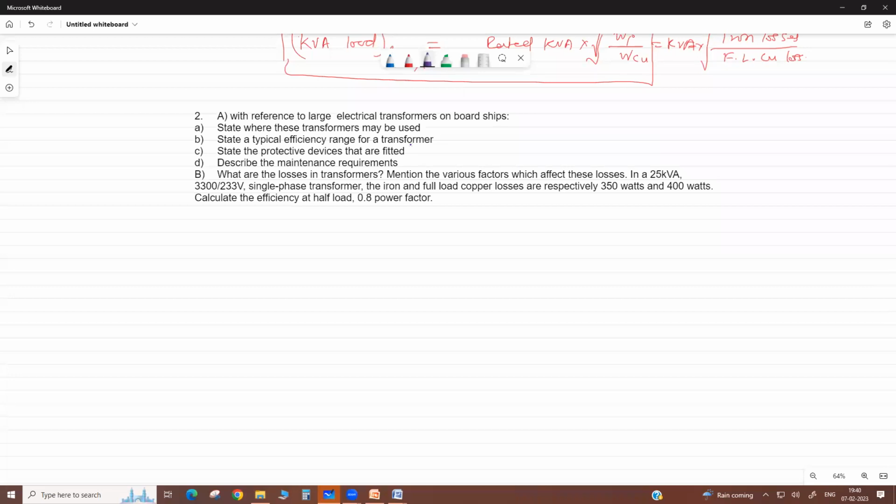But in dry type, dust is the main factor. We clean the dust because when dust is deposited on the winding, moisture will be there, and then leakage current will be there. So we remove the dust, cleaning of the dust. Then continuous monitoring of your temperature sensors.